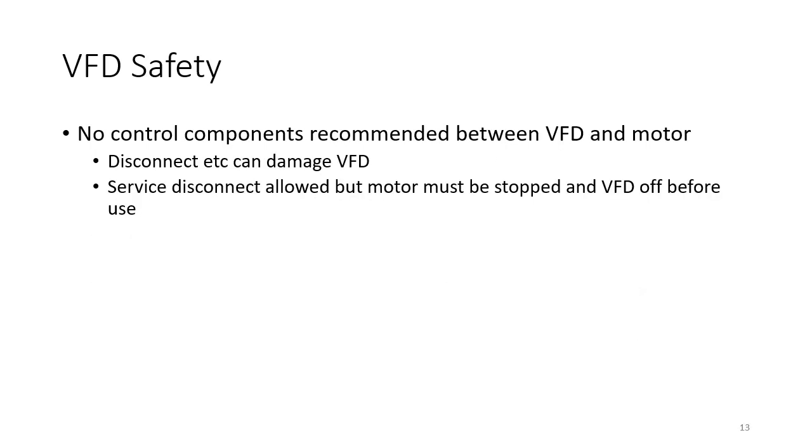Now, for safety reasons, no control components are recommended between the VFD and the motor. If you were to suddenly disconnect the motor while the VFD was running, that can cause severe damage to the VFD and destroy it. You are allowed to have a service disconnect, but the motor must be stopped and the VFD must be powered down before use.